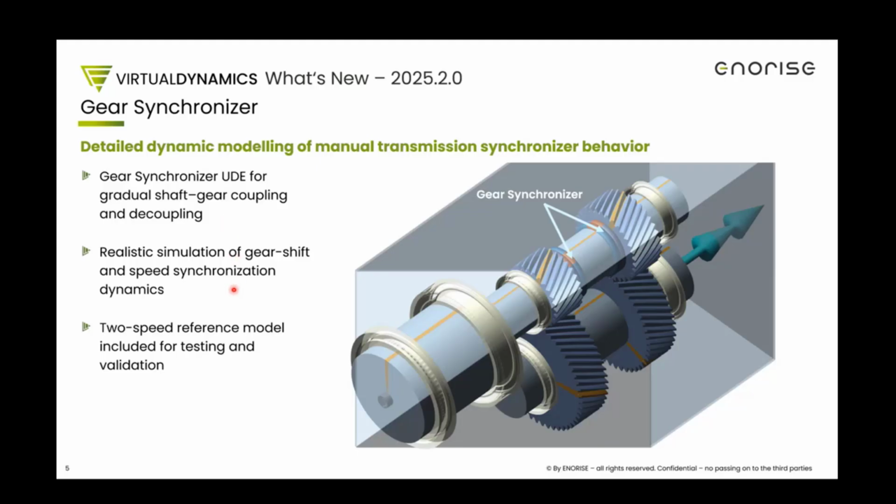Yeah. So the two phases which I mentioned. First you have the possibility of defining a friction clutch, right, which will reduce the speed delta between the shaft and the gear using a torque buildup. And once the speed delta has reduced below a particular threshold, which the user can define, the dog clutch would engage for a fit coupling of the shaft and the gear, right?